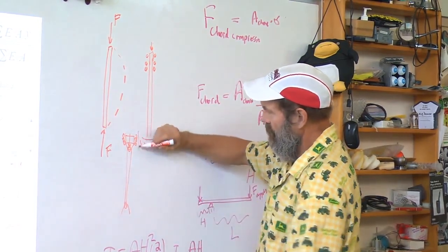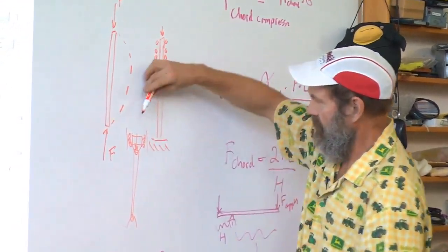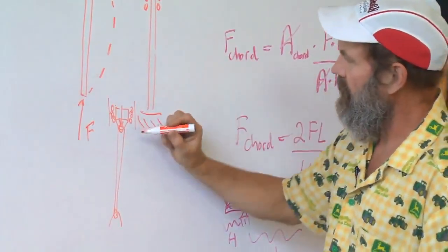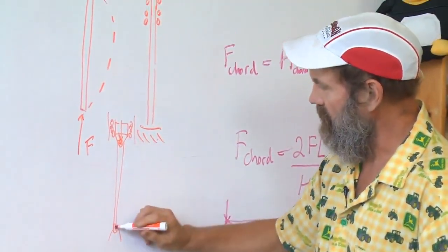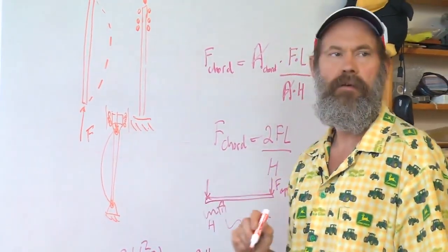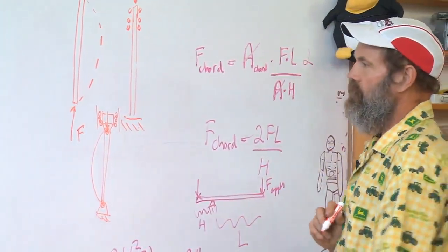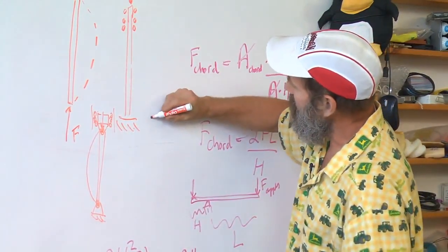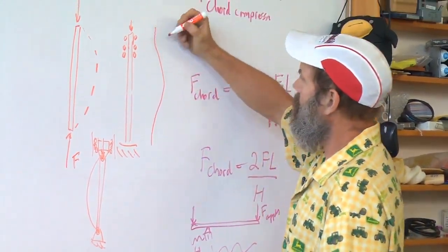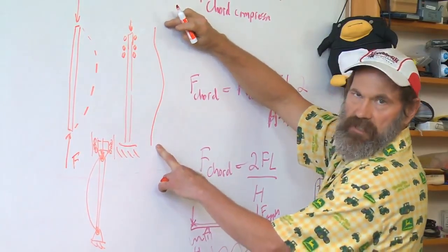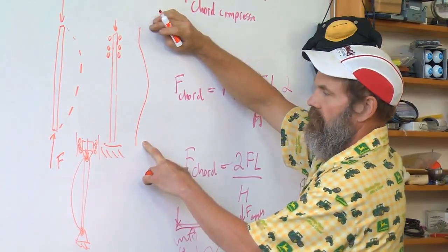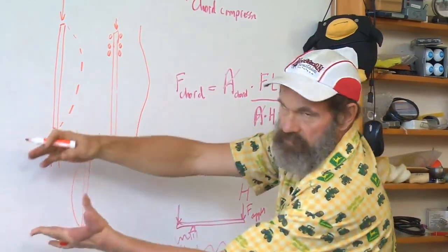These represent little rollers, such that this motion is vertically downward. It won't buckle over sideways, but this is a no moment constraint, so the thing can come out like that. So if it was built in, the mode shape would be different, which is much, much stiffer, almost an order of magnitude higher load capacity than something that is free to just pop out.